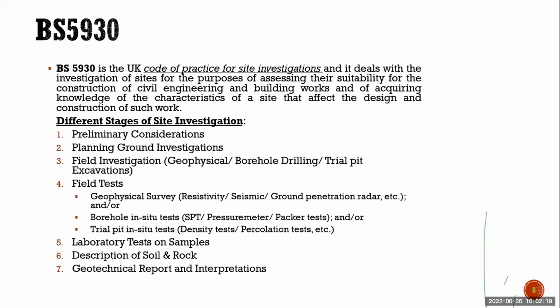As per the British standard, here we are going to see what the different stages of site investigation are. First, preliminary considerations. Second, planning ground investigations. Third, field investigations, which can be either geophysical, borehole drilling, or trial pit excavations, or a combination of everything together.